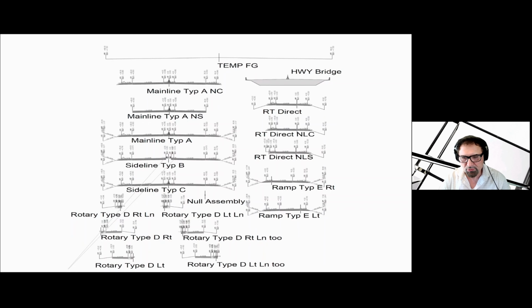Of course, when you get into corridor modeling, then you start also working on development and managing your library of assemblies. Here are all the assemblies used in the model. And you can see that on the main line, like I said, the region when there's no connection points, that would be actually, this is further work done after my presentation class to add the retaining walls.